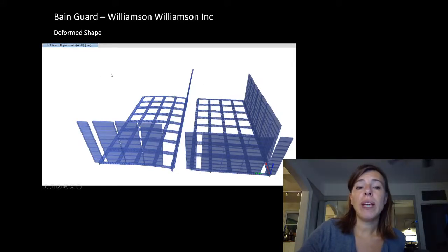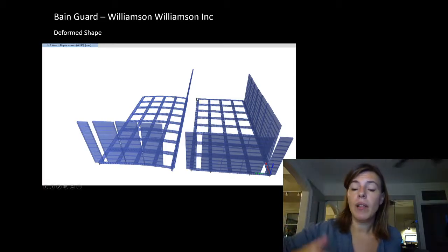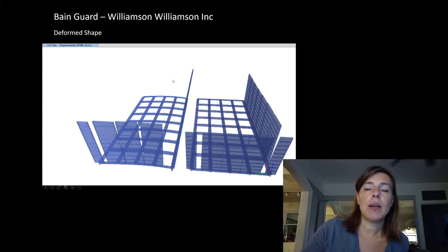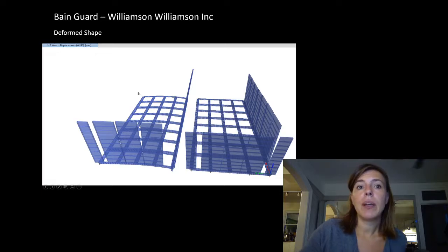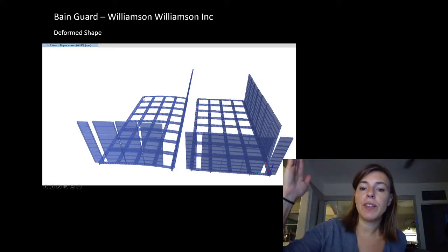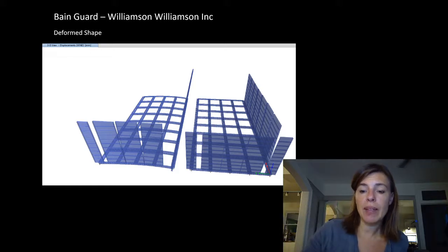Here it is with wind on it, because wind actually was a solid glass wall, makes it a wall. I didn't have pickets that wind could get through. So this ended up being the governing case. You can see for wind on this outside face wall, my steel actually arching up. And so this arching needed to stop by the time we got back to this weight. That any uplift, that this wasn't trying to flip up in the air. If that was trying to flip up in the air, we had a system that didn't work.